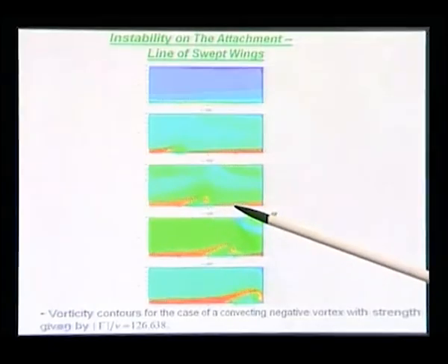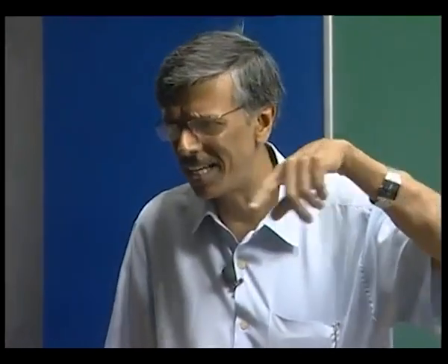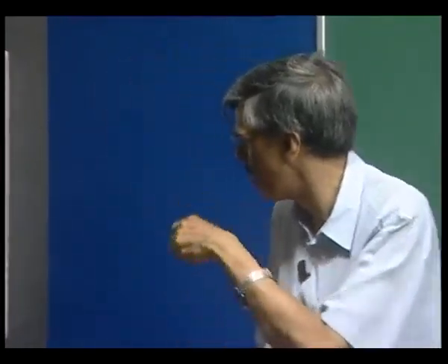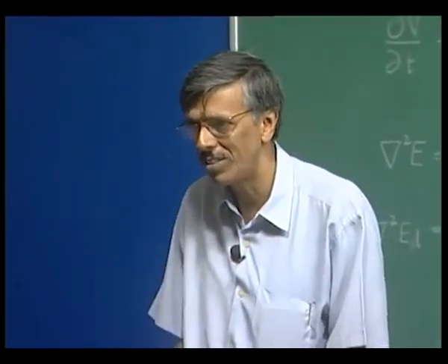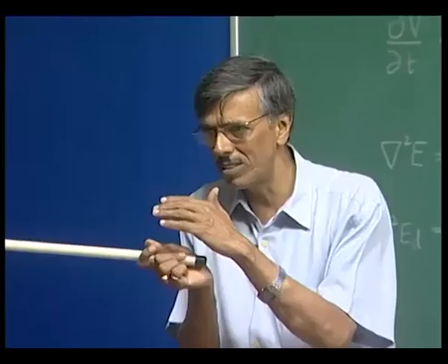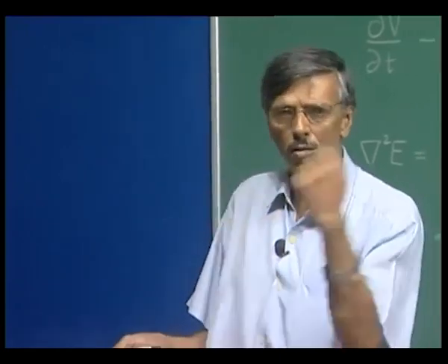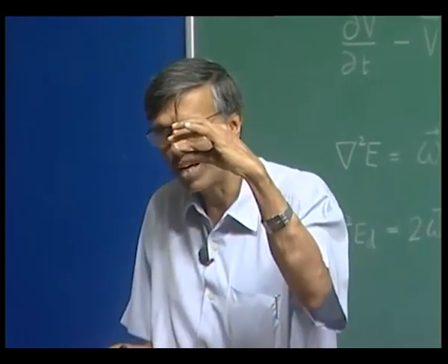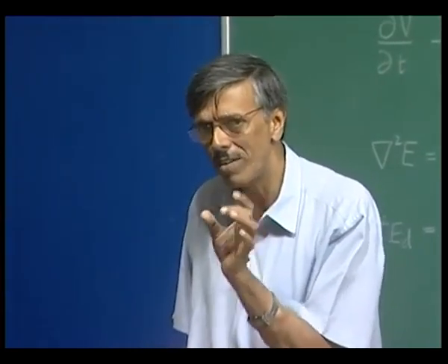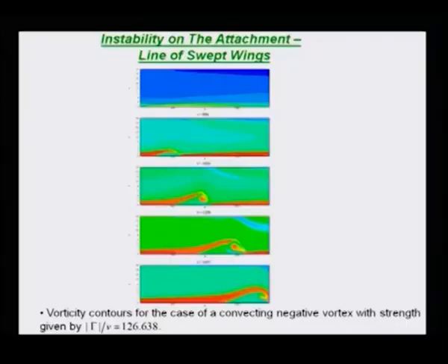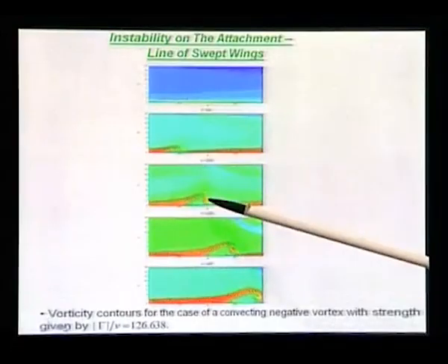And as it goes along, recall from that sketch of flow past a rotating and translating cylinder how the streamlines converge and diverge. For this case, streamlines diverge just behind the vortex, but if you go a little further down, the streamlines are again narrowed down. So, this adverse pressure gradient is very localized, and that is what causes a single vortex to be created.